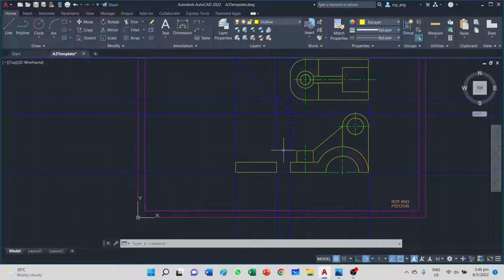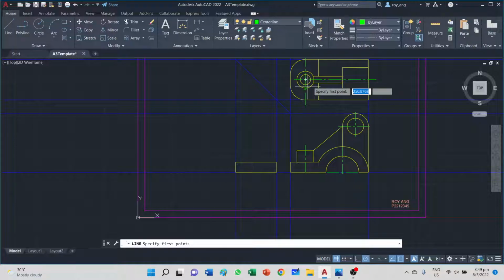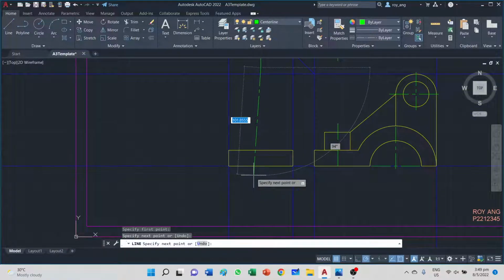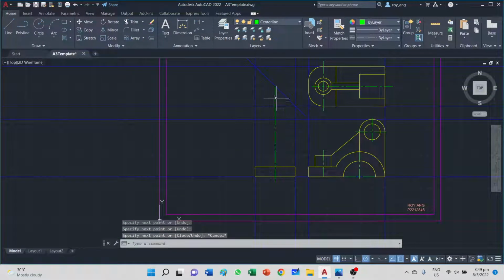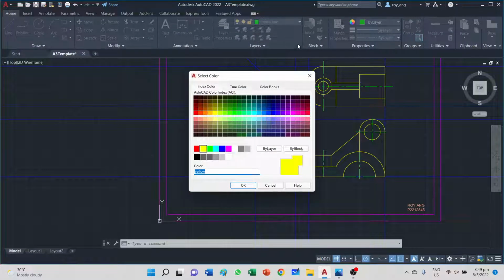Alright. Now what would help is a center line, so that you can draw it a little bit more efficiently. Okay, and I'll draw my center line here, and my center line comes down here, and I don't need this part, so I delete it away. Okay, now what will happen is I am going to make use of projection to draw my outlines. Okay, and I'll draw from bottom up.